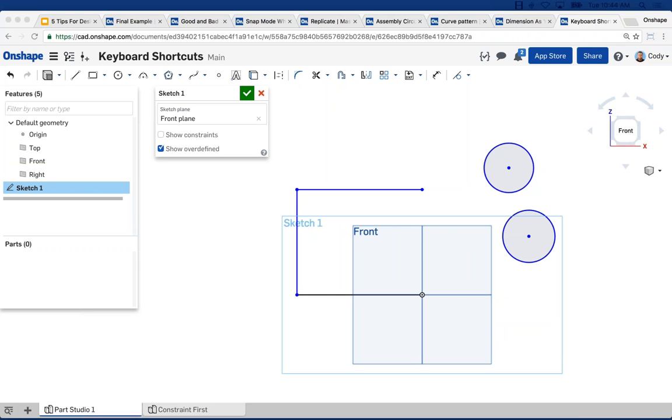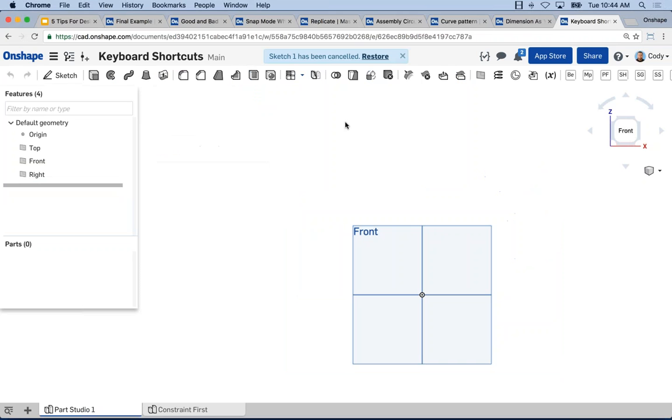Can you add angles to dimensions on the fly? No, because angles involve two things. That's the limitation of dimensions as you go. And the idea behind it isn't necessarily to fully define everything. It's just to add dimensions for things like size of geometry. You still will need to add other dimensions, of course, to really properly define your intent. Can you window select? Yes. Can you print out the keyboard shortcuts, which is, I believe, what you're referring to?